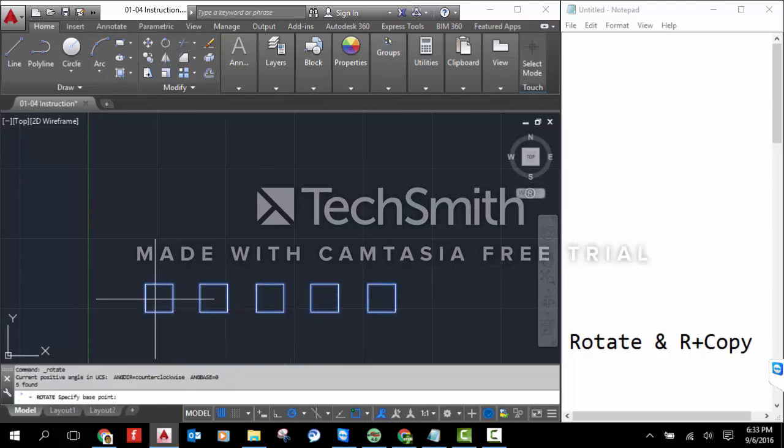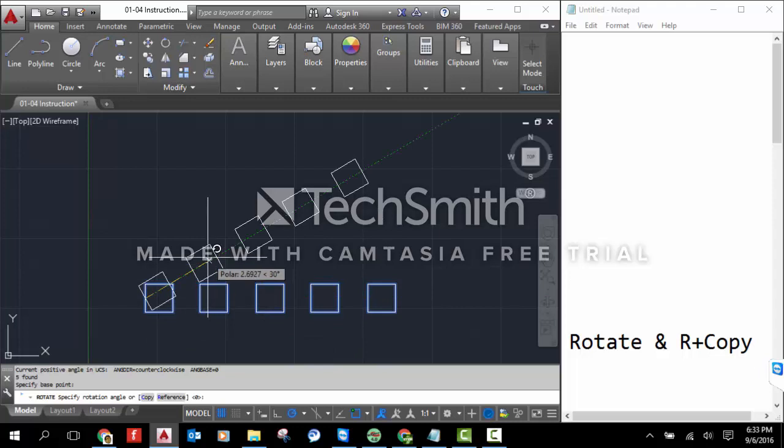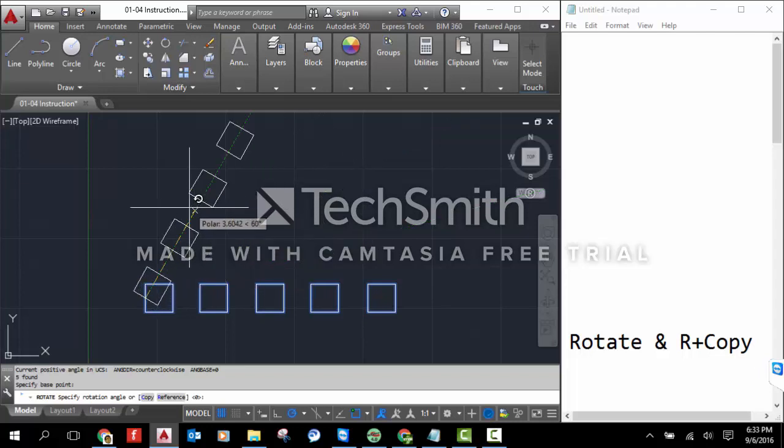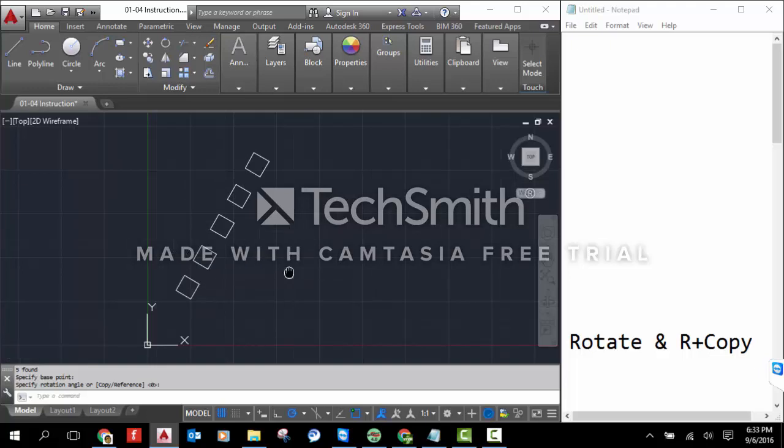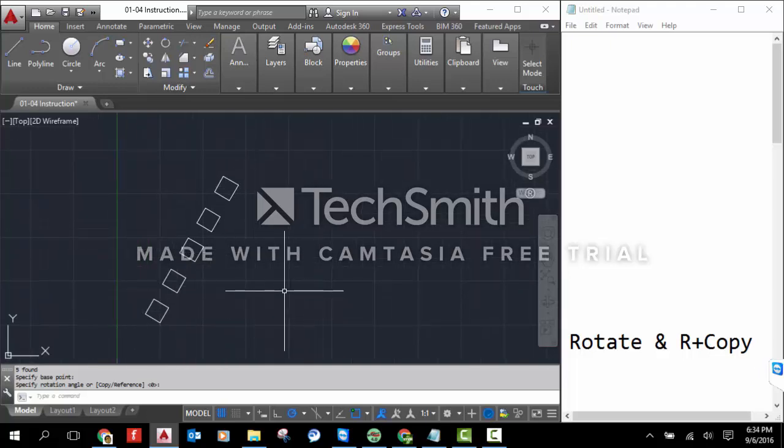So I'm going to specify the base point as this midpoint on the far left rectangle. And I'm going to click on it. Now you can see I can rotate it. And because I have my polar tracking on, it'll actually lock in at each of those degrees, 30 degrees, 45 degrees, 60 degrees. I'm going to click 60 degrees, and you can see it rotated. Those 5 pieces moved back over.